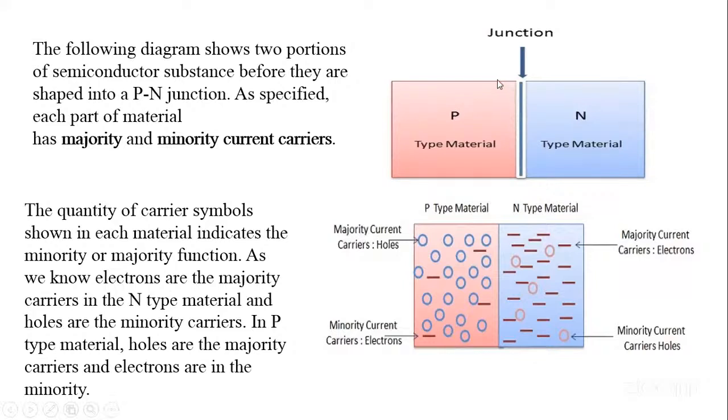Between the boundary, they begin to form a depletion layer. That depletion layer will keep expanding, because once an electron fills a hole, it becomes ionized and immobile, so it will remain there. The more holes that are occupied by free electrons, the more the depletion width expands.